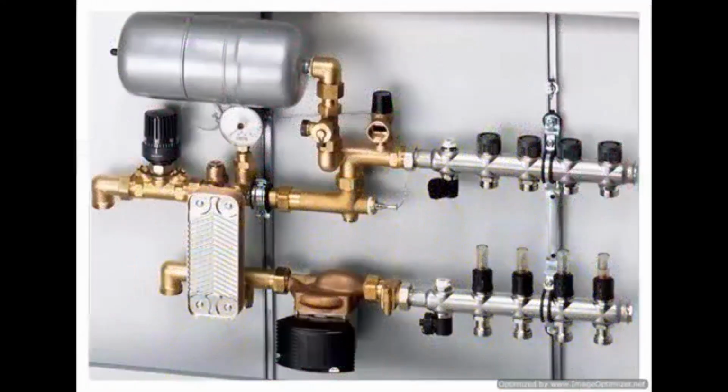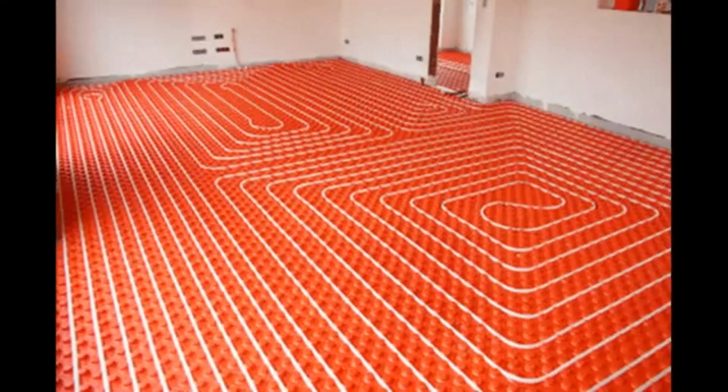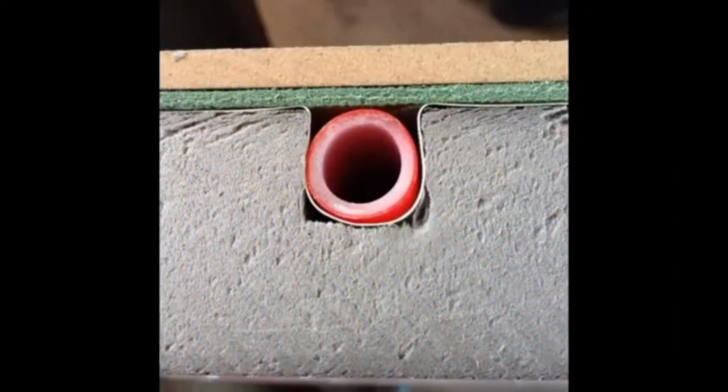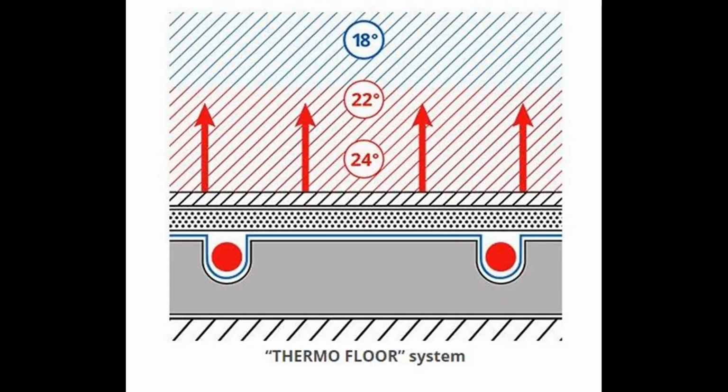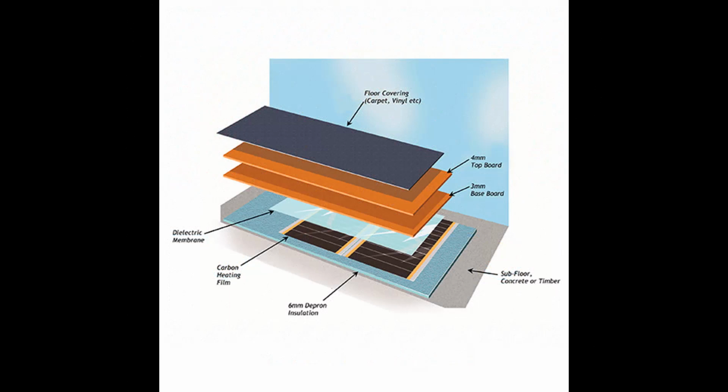What is important in rented premises? Such a system, when we use heat exchangers, can be mounted in an apartment that connects to a city heating system. This system also has a cost comparable to traditional types of underfloor heating. This system also has its drawbacks. The thickness is 40 mm, and this must be reckoned with. Electric underfloor heating is thinner.